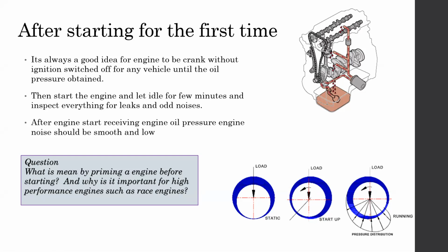Engine will start to rotate. But the advantage here is that in this situation, the piston is not rotating the crankshaft, but the crankshaft is rotating the piston, right? There's no highly pressurized air on top, and no explosion happening inside the combustion chamber. So the forces acting on the crankshaft, camshaft and other components are less, and there's less possibility of damage. So before the first run, it's always better to prime the engine.